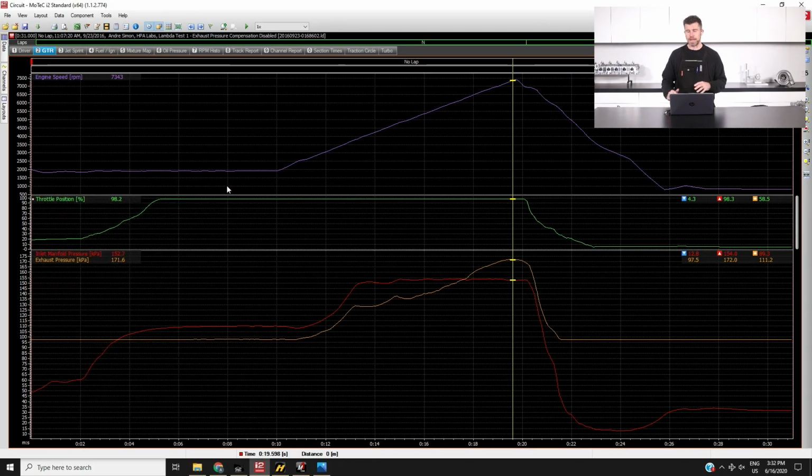That's actually pretty good. If you test a lot of factory cars, you'll find that factory turbocharged cars, because the manufacturers are so interested in trying to get that snappy low RPM boost response that gives that high torque feel, they really sacrifice high RPM flow for that low RPM boost response, and you're quite likely to see that on a modern turbocharged factory car, the exhaust manifold back pressure could be as much as 2, maybe even 2.5 times the inlet manifold pressure, meaning that if we're running 15 psi of inlet manifold pressure, we could easily expect our exhaust gas back pressure to be at 30 psi or above.